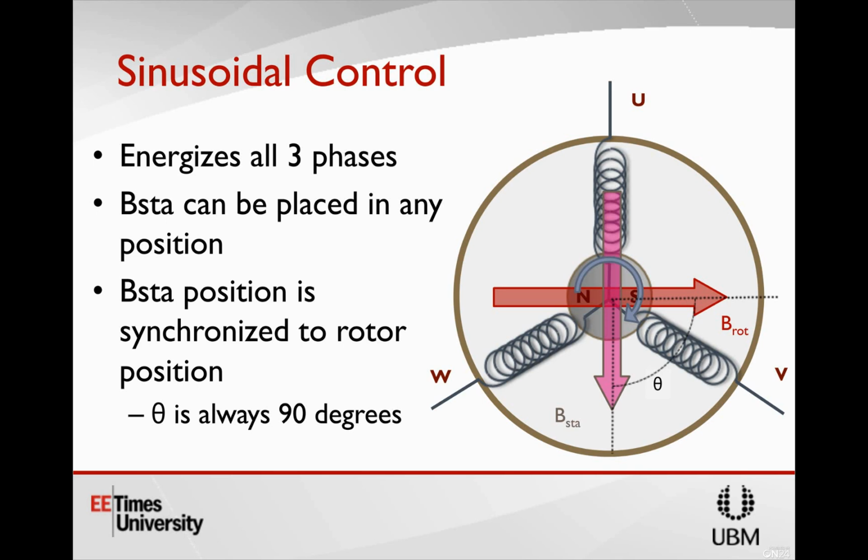Because what we do when we talked about align and go is that we're just picking an angle. It can be completely arbitrary. So worst case, your motor is perfectly 180 degrees away from it. So that's your absolute worst case. That means the motor has to rotate all the way around to 180 degrees before it can actually start working correctly. Now what if we had our Hall effect sensors and we could cut that down to within 60 degrees? That's a much better situation to be in in terms of this align and go technique.